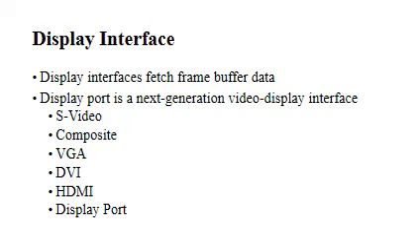It is still widely used but might be replaced eventually by DisplayPort. The digital signal has 24 pins. The extra 4 pins sometimes included are for some analog signals. The interface is designed to transmit uncompressed digital video and can be configured to support multiple modes such as DVI-D, DVI-A or DVI-I. It is possible to buy DVI to HDMI converter cables.